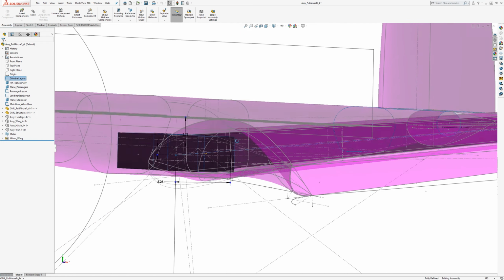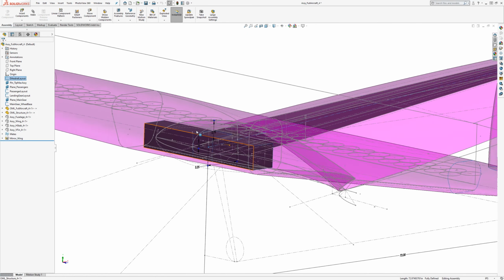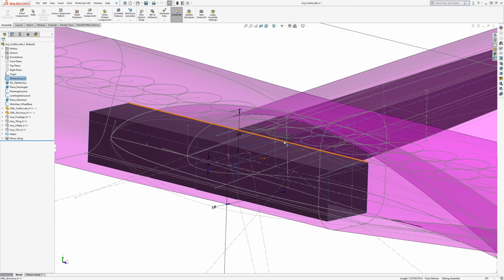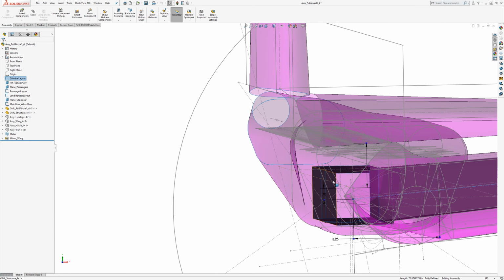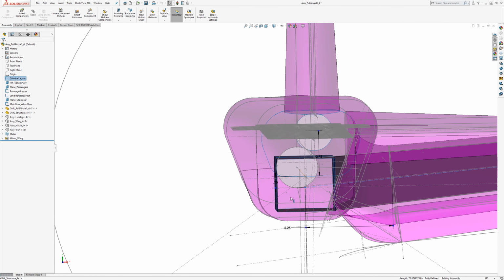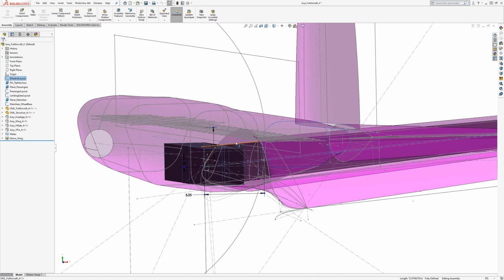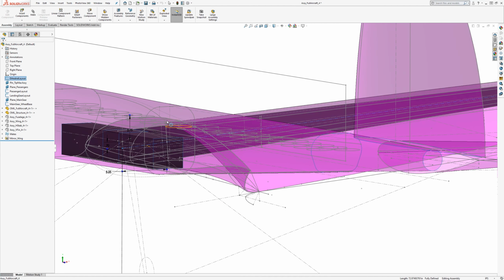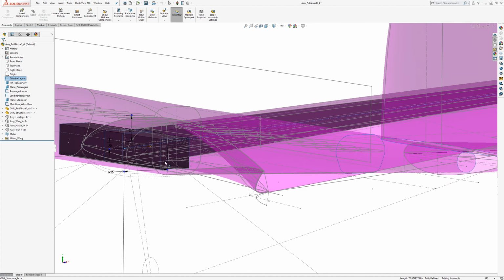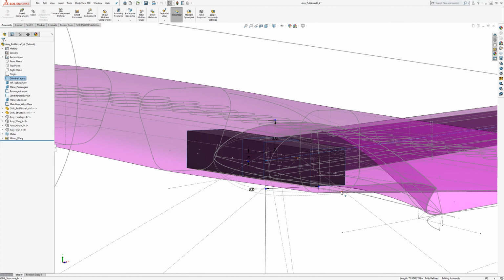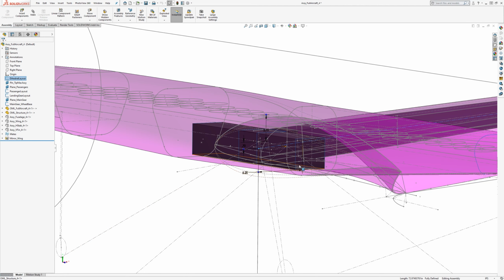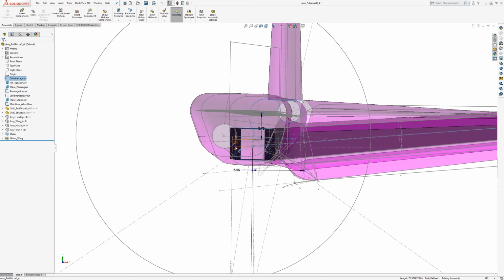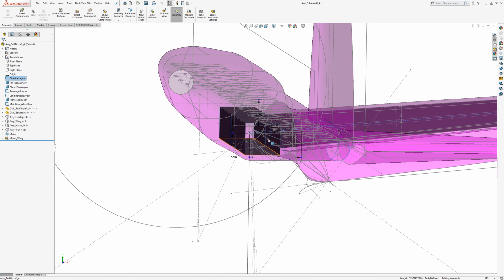And then there's going to be some fittings, some frames that take care of all that load and give some space for cargo in here, and allow the wing loads to go around the keel beam, and the keel beam loads to pass by that wing box, and in a way that it's all kind of meeting in the same area here. So that was a design intent, and this does that design intent.